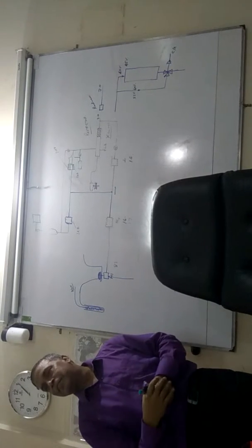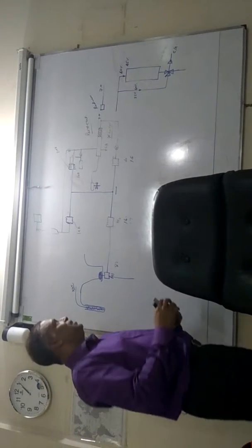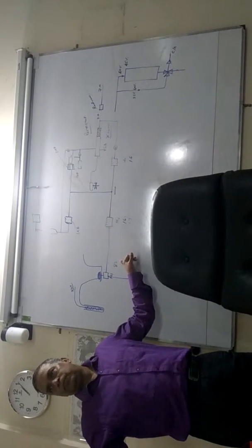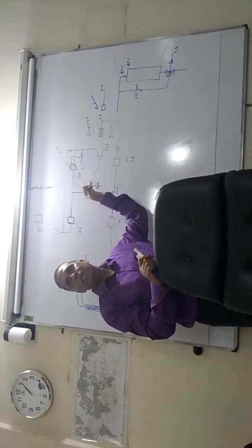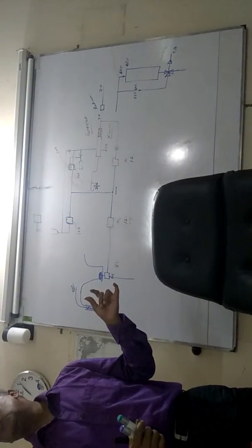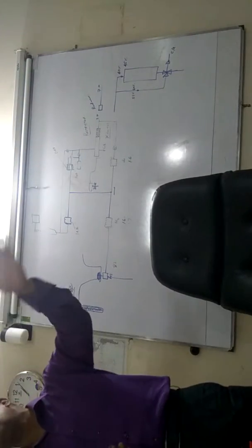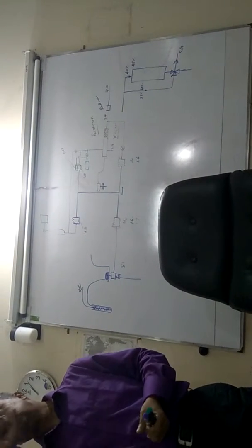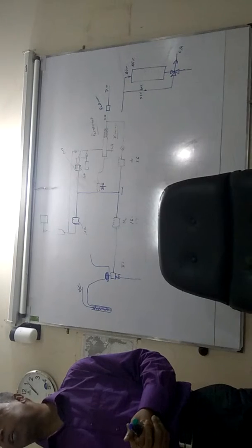So this means a little bit of a problem. Because if it is 81, 1 degree rises, for that it will move a little, it will go somewhat closer, and if we say this is such a small motion, so we understand that for just that much, the flapper may be seen to close the nozzle completely, because it moves only a little. You agree? Fraction of a millimeter we are talking about here.